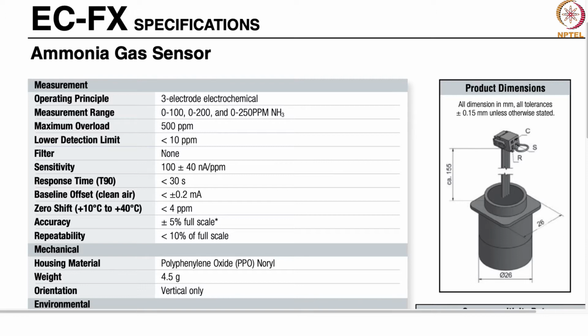So you'd have a limit like that, and then there is actually a sensitivity number. The sensitivity is, in this case, you have a certain concentration of the ammonia gas, and you're trying to extract a parameter at the receiver, and that parameter, for an electrochemical sensor, is a current, this electrochemical current that comes about.